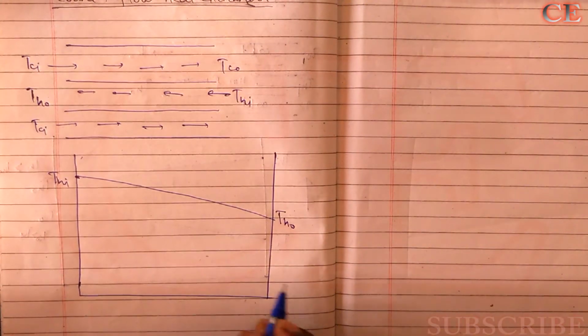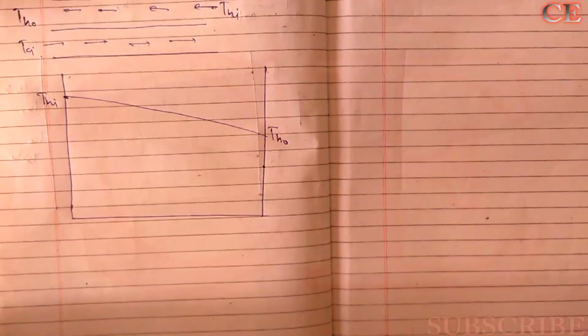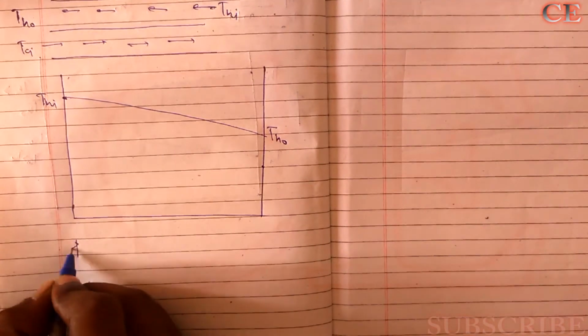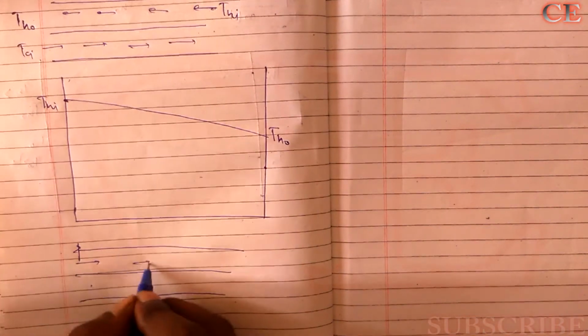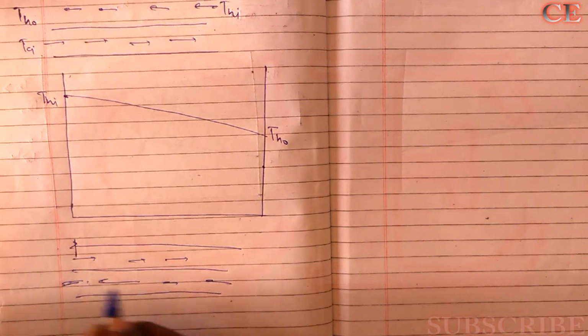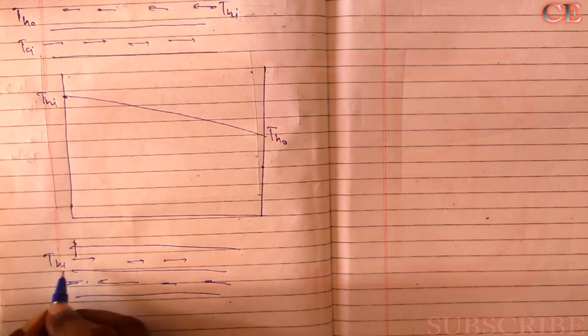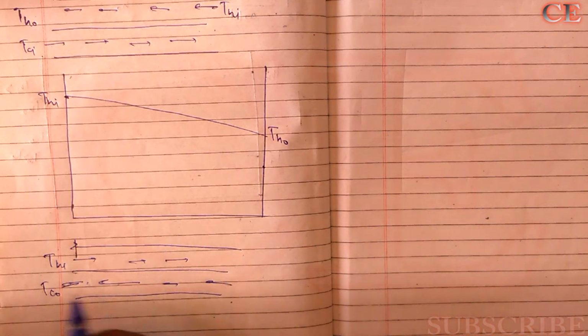THO. Now here is temperature TCI. Suppose one more thing, that hot fluid is running in this direction and cold fluid is running in this direction. Now what will happen? The THI would be on the left side and TCO would be on the right side.